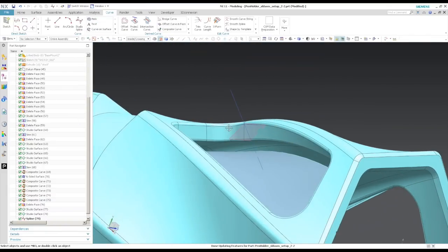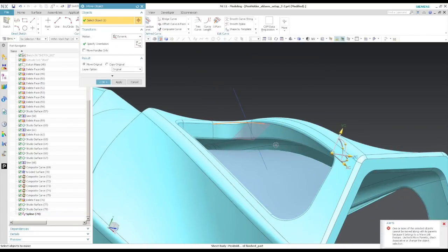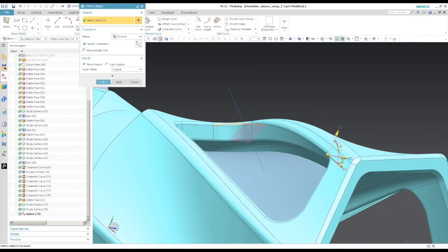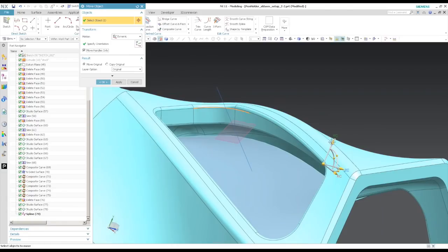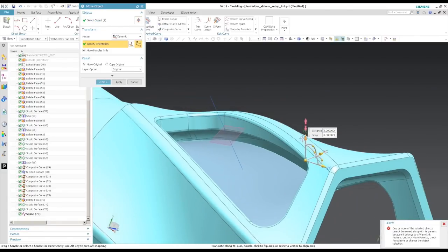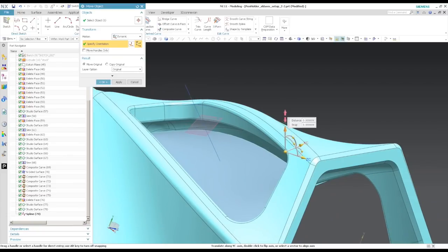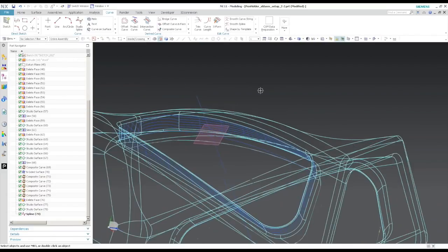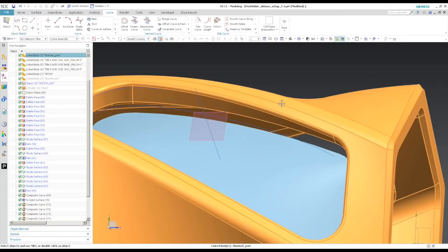So we'll say OK, and then we can copy that spline and basically translate it down. We can make the translation normal to the edge. So I just moved that handle normal to edge, and now I can drag that down, and I'll say copy. Then I'll switch to wireframe, or you can hide your model.